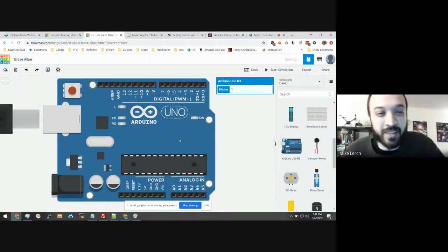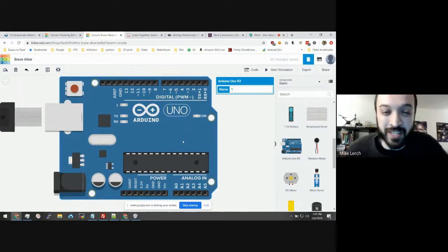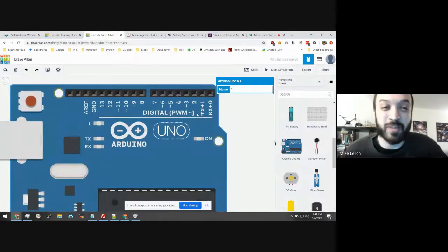All right, so the really neat thing about Arduino input and output pins, which are very similar to Raspberry Pi, so it's good that you brought up both because they both have these types of abilities, is these pins are input and output. So in the software, you can identify each pin individually and whether the Arduino should be talking on that pin, so it's outputting, or if it should be listening on that pin, so it's inputting. Every pin can be input or output. And when we see a squiggly mark here, a tilde, that means it's a pulse width modulated PWM pin.